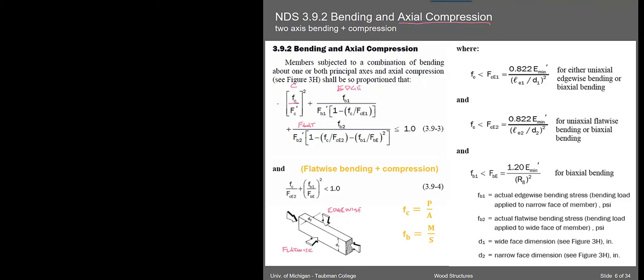And you've always got the compression aspect. Now, it's kind of interesting the way this formula is worked. This is just the ratio again, right? That's the same ratio of actual stress to allowable stress. And then they multiply it by a factor that's supposed to be a 1. Okay? And this factor that they multiply it by, you can call an amplification factor.